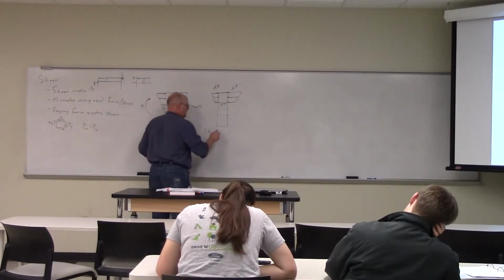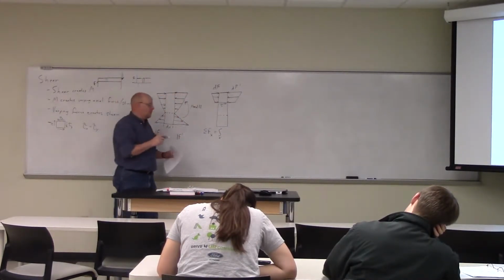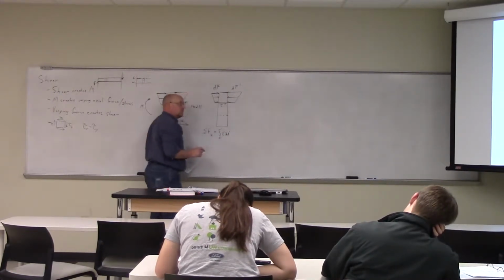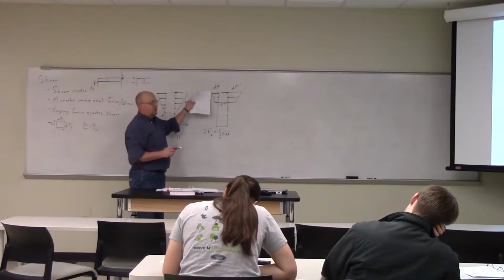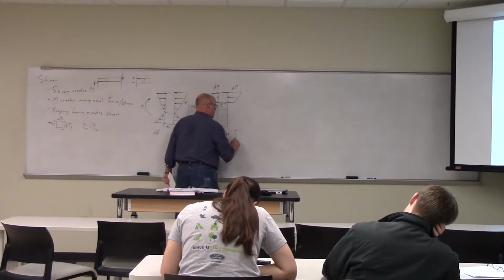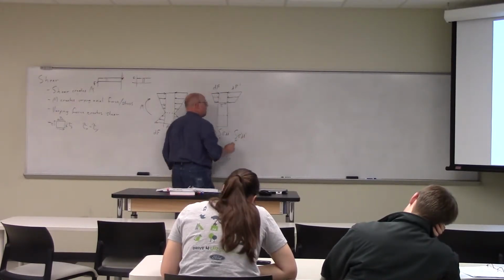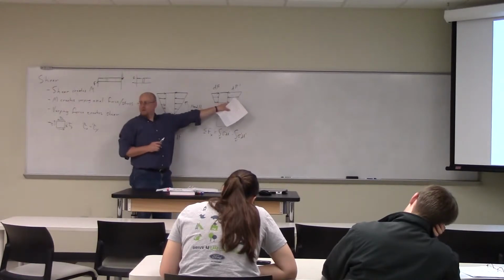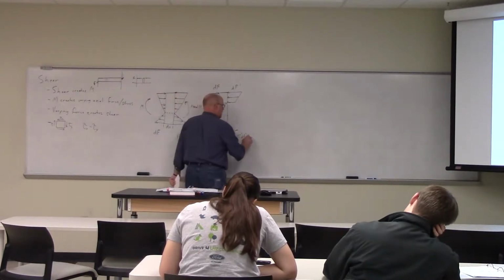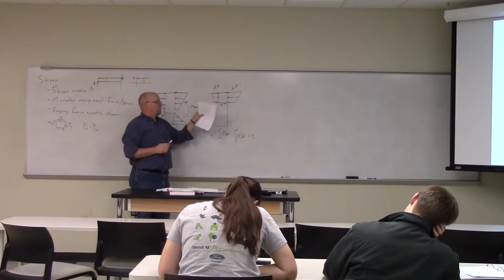Well, I have the integral over A prime, just that top section of the canned ham, of sigma dA prime. That's what's on the left-hand side here. It's a positive force. Minus the integral over A prime of sigma prime dA prime, which gives me the force pushing back, plus the shear stress times the area on which the shear stress acts.